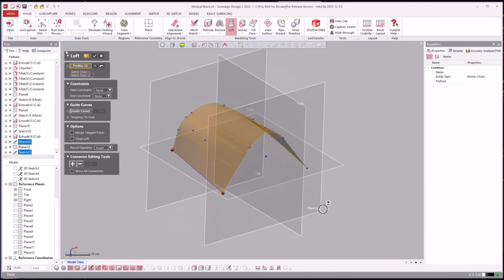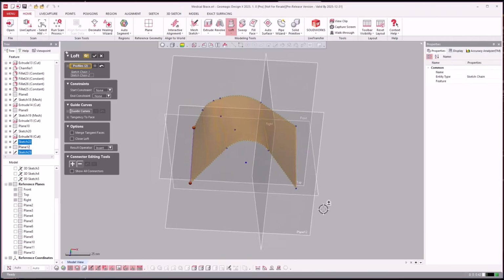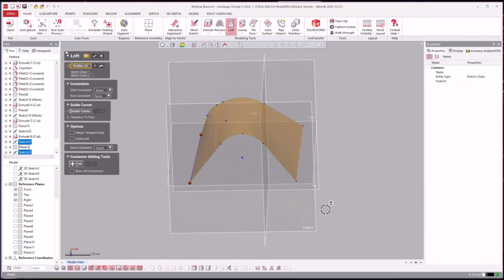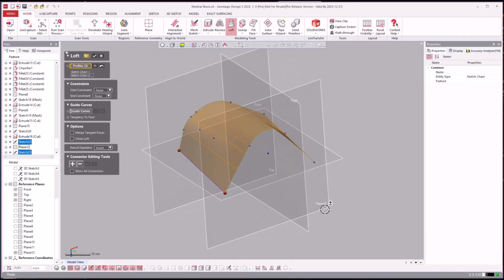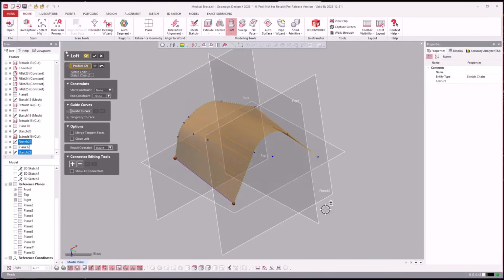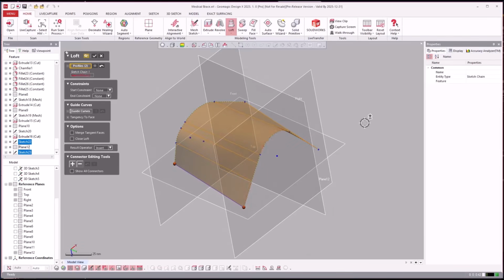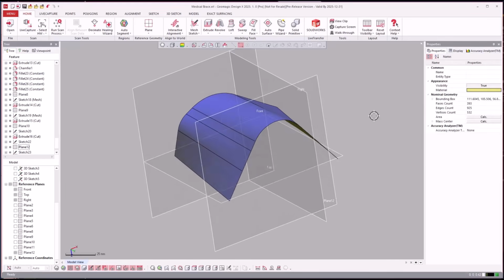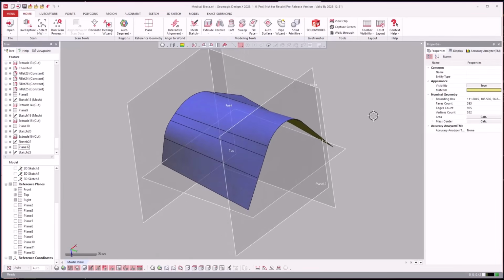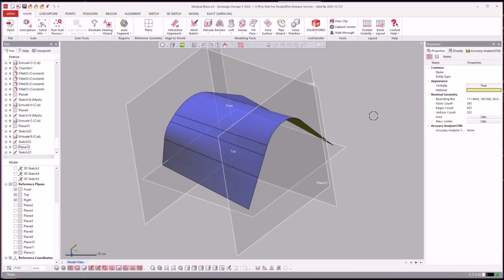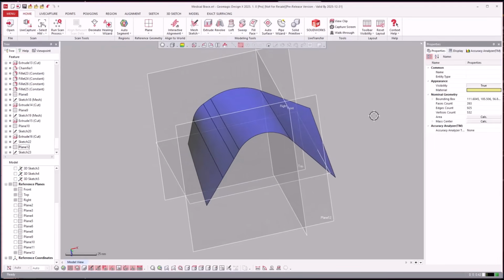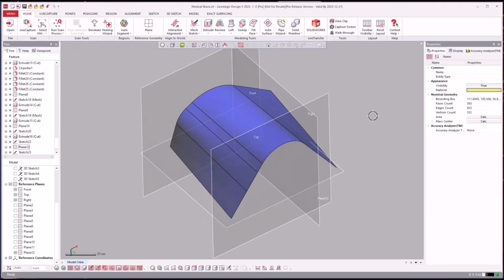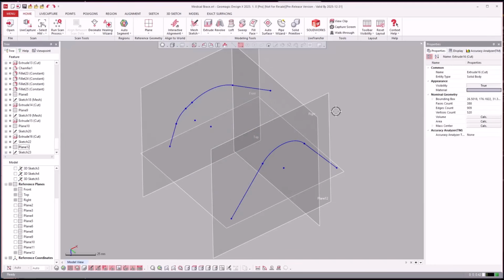In this instance, it's going to do a reasonable job. But sometimes the line segments don't match up well to loft and make a nice clean loft. So we'll go ahead and accept this. And this is an okay one. I could have made it a messier loft by doing more segments and less segments on each side and not having them translate over well. So we'll go ahead and undo that.